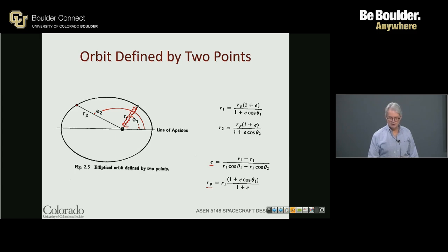If we waited time t later and did the same thing, broadcast up to the spacecraft, looked at the return information that came back and calculated a second radius and a second distance, all of a sudden we're starting to figure out what the orbit properties look like. So this is in fact what we do. We launch a spacecraft in orbit. It doesn't really know where it is. The launch vehicle might give us the location and vector once things leave, but we have to start looking at the spacecraft and figuring out how far away it is, and using ground information what angle it's at, so we can start to build its properties.